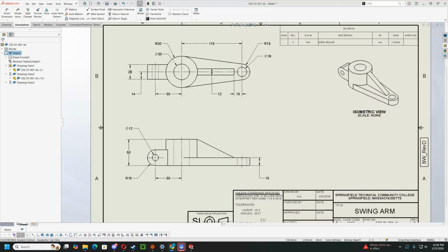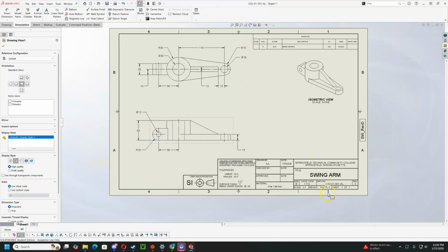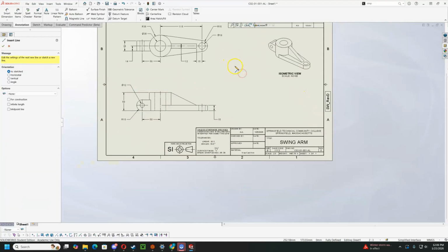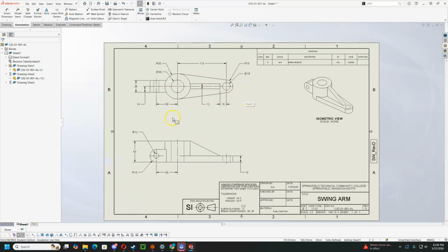Sheet scale matches drawing scale. These are using the sheet scale, so yes, they match the drawing scale. The exception is again the isometric view. That note is mostly there to prevent you from overriding the scale on these views and forgetting to change it here. Just to remind you that these need to be the same.